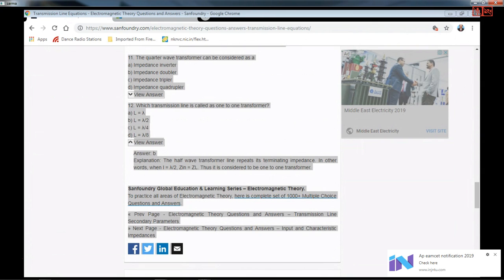Standing wave ratio is represented as S, and it is a dimensionless quantity, and it is only a real number. Why is it a real number? Because it is simply the ratio of two magnitudes. The magnitude of the voltage wave when there is a maximum combination of reflected and incident waves. Similarly, a minimum also is going to be there wherever the phases oppose each other, thereby Vmax to Vmin. They are simply numbers, and the ratio is again going to be a simple real number.